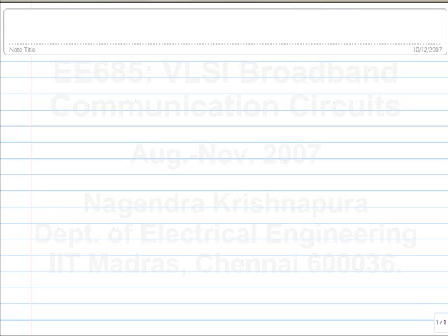So far we have discussed two types of equalization, the feed-forward equalization and decision feedback equalization. So we'll just discuss some more implementation issues with decision feedback equalizers and wrap up the topic. The main advantage of decision feedback equalization is that to achieve the same amount of ISI cancellation, they don't enhance the noise, okay? Because the feedback part is digital, which has no noise.